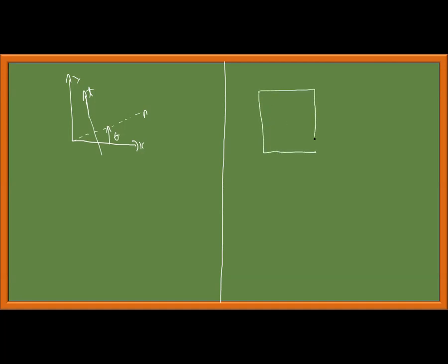This is the state of stress in 2D. Sigma x, sigma x, sigma y, sigma y. Normal to the plane is tau xy. As soon as you write that, opposite the plane you should write this. Arrows should meet. Normal tau yx, tau yx. This is the general state of stress. For a given problem, this is a stress condition. He has given a state of stress for a point. He has taken a plane, he has taken a body. At this point, he has given the state of stress: 50 MPa, 60 MPa, minus 30 MPa.